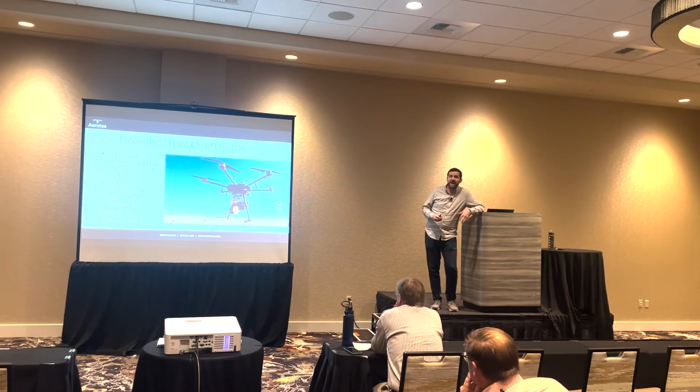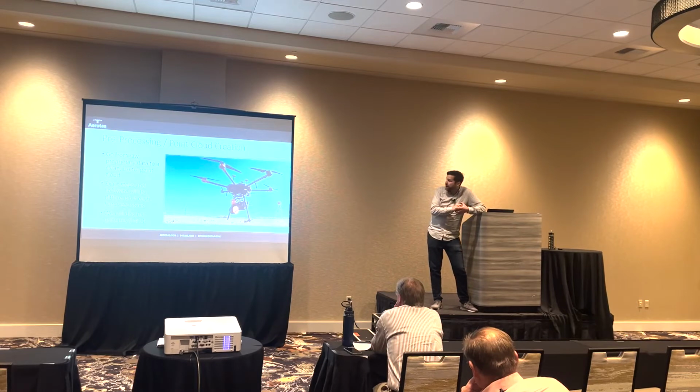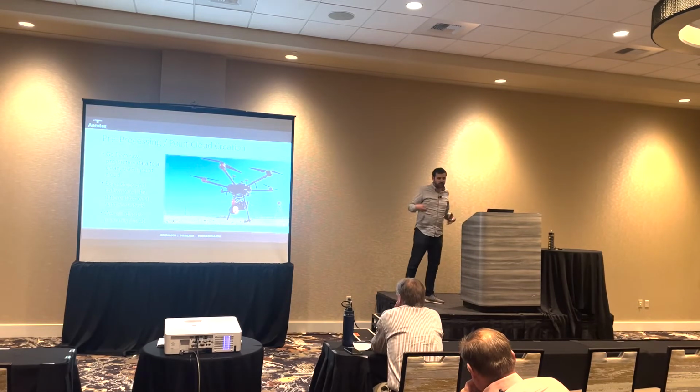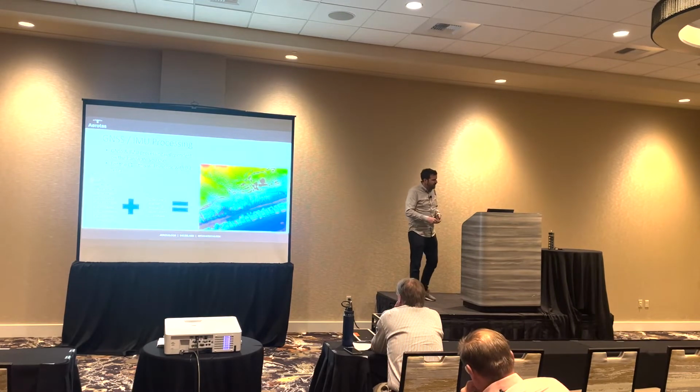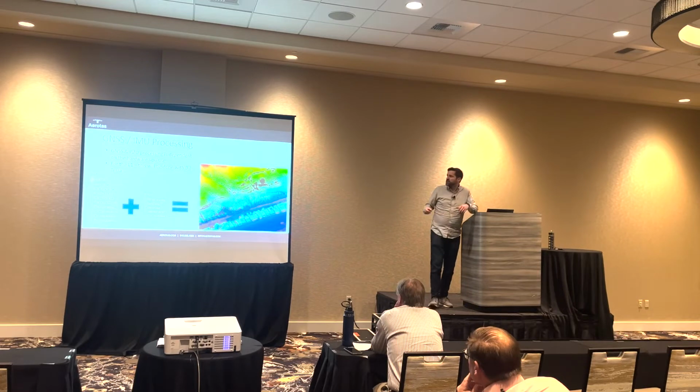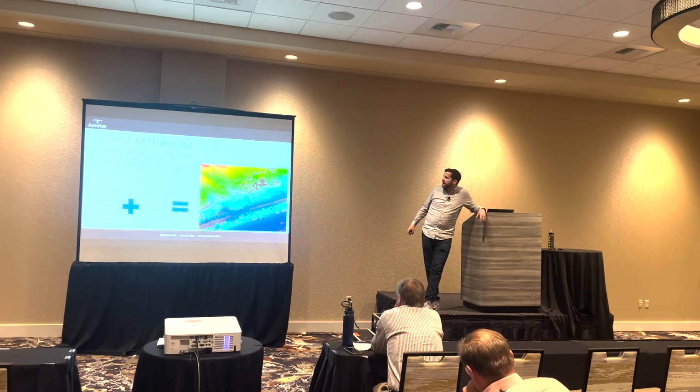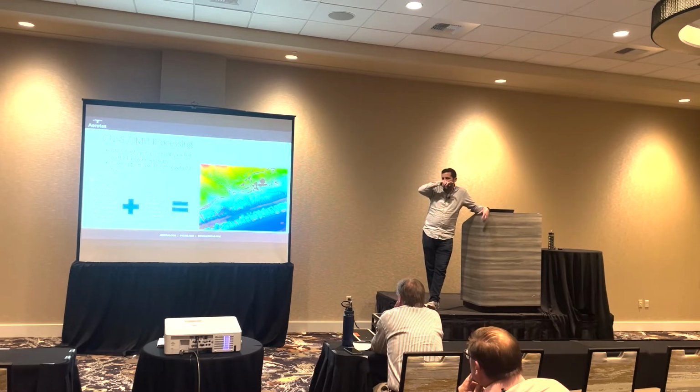The thing with this LiDAR pre-processing is that the exact steps are going to be different for every hardware stack. I'm going to be covering a little bit of what it looks like on the L1, just because the DJI L1 is the most common LiDAR system out there. But typically each LiDAR system will have their own proprietary software. So you kind of have to do this yourself or talk to whoever you bought the LiDAR drone from on the pre-processing step. But that's where, like I said, you take your GNSS and IMU data and you put it all together in DJI. It's a software called DJI Terra to create that actual point cloud.